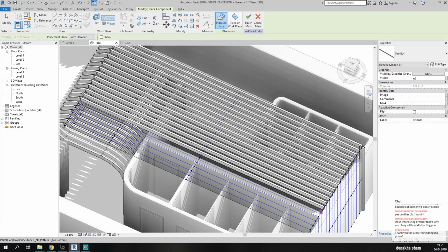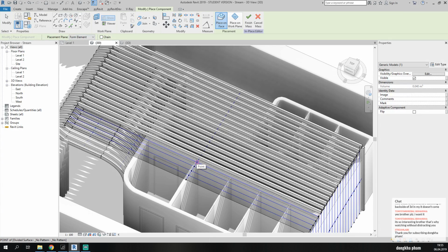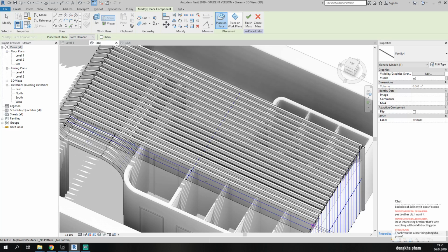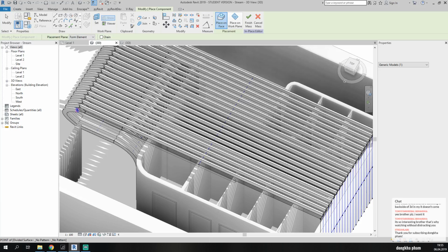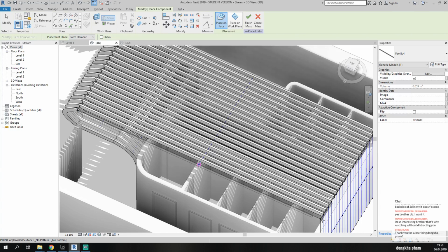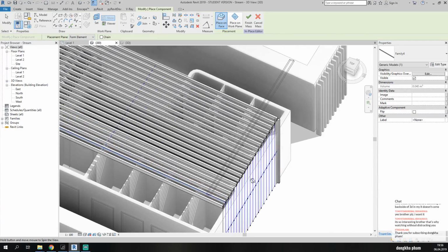Like a few more. Oh, by the way, why am I using the knots? I didn't say. Because if you change the shape, your knots will follow your shape. So it means I don't need to recreate the model, because my knots will keep everything it's based on. So that's why I'm using the knots. Yes, I can create it faster. I can create it like a messy thing. But if I change something, I will have to change everything. So that's why.